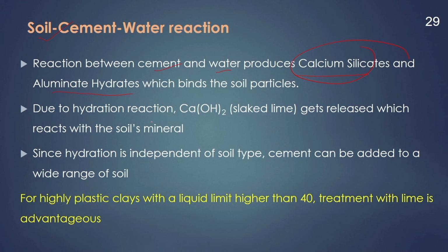Due to this hydration reaction, the slaked lime, that is calcium hydroxide, gets released, and this will react with the soil mineral. Since the hydration is independent of the soil type, cement can be added to a wide range of soils. And as I told you earlier, for a highly plastic clay with a liquid limit higher than 40, the treatment with lime will be advantageous.